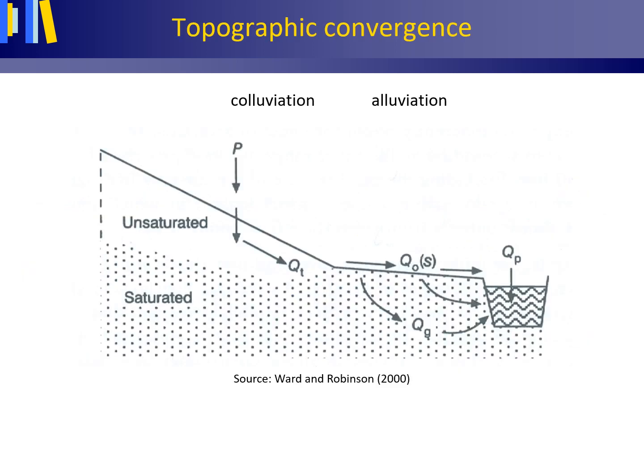Often, but not necessarily so, variable source areas are located near the channel network that drains the area. The latter has to do with processes such as colluviation, the deposition of sediment through the action of gravity at the foot of a slope, causing the hill slope angle to diminish in the direction of the stream, and alluviation, the deposition of sediment by streams, causing areas near the stream to be flat, that is, when viewed in cross-section.